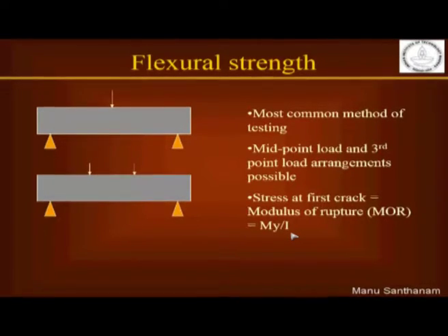Okay. So, in the case of fiber reinforced concrete, you will probably need to apply a slightly different technique where you will have to study what happens even after the first crack appears. For normal plain concrete, which we are testing for a mix design, for example, the first crack load is the only thing that is important, because the concrete specimen does not remain after that, it just splits, it breaks into two halves.